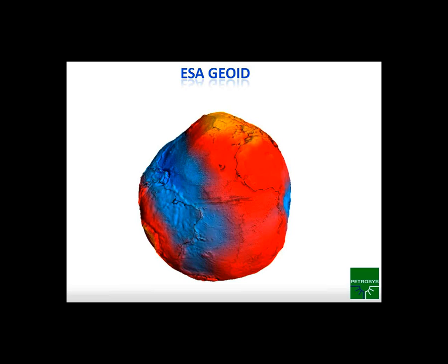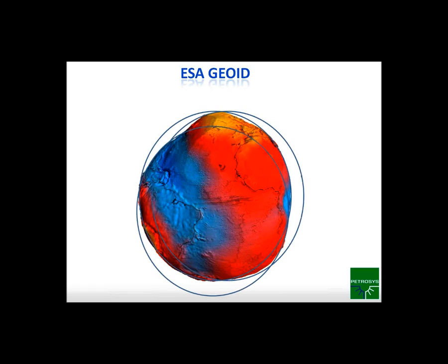So what you do, you take this geoid and you try and simplify that down, and you apply what we call a spheroid. So it's kind of a best fit type of object. You can see that the surface of the spheroid is going to match up, and you can orient or place that spheroid in different areas around the geoid so that the edge of the spheroid matches up, or comes into line with sections of that geoid.